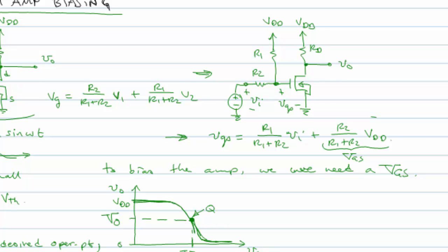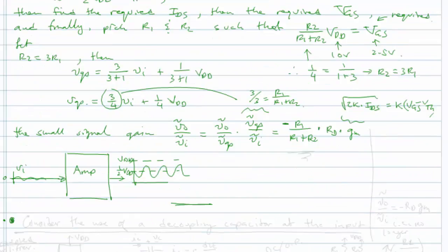And so we can actually change the operating point of the amplifier by adding an offset to the input voltage. And what we want to do now is consider how we might be able to solve that problem so that the input can pass the signal that it wants to have amplified, but not be able to alter the bias point of the amplifier.